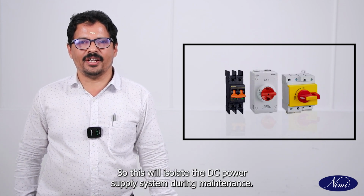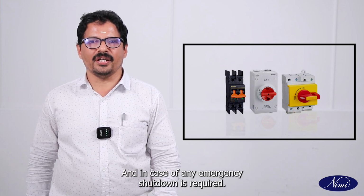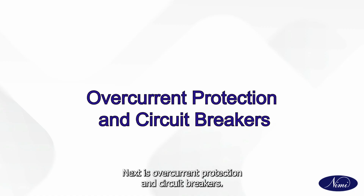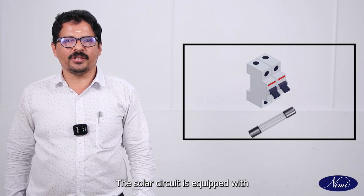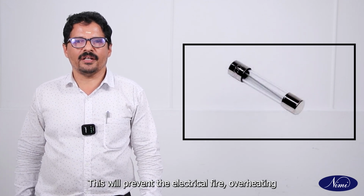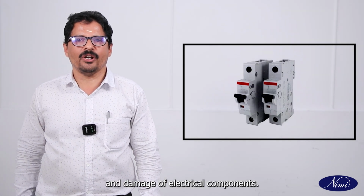So this will isolate the DC power supply system during maintenance and in case an emergency shutdown is required. Next is overcurrent protection and circuit breakers. To protect against overcurrent, the solar circuit is equipped with circuit breakers and fuses. This will prevent electrical fire, overheating and damage to electrical components.